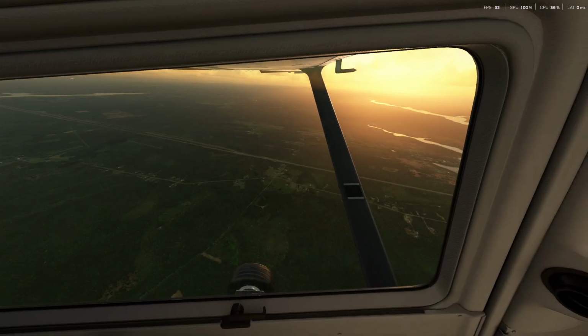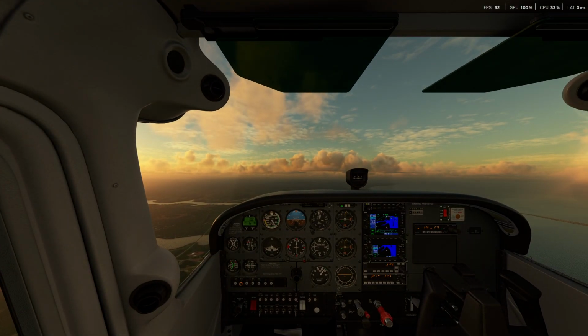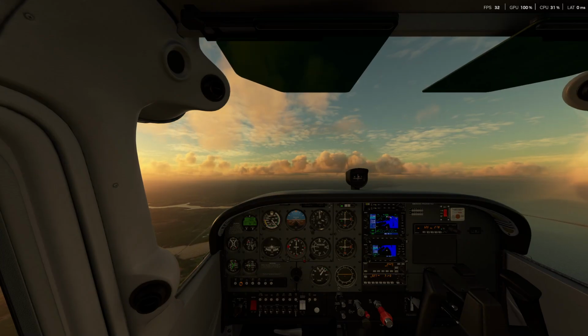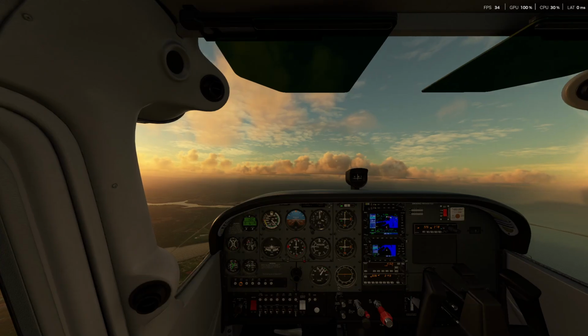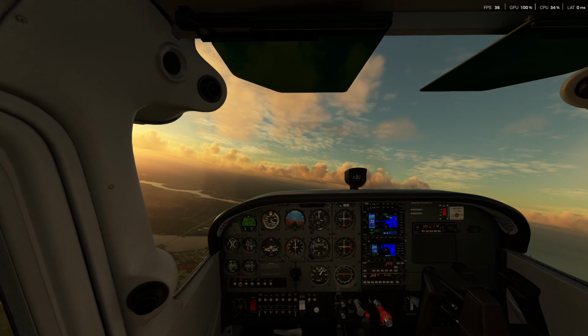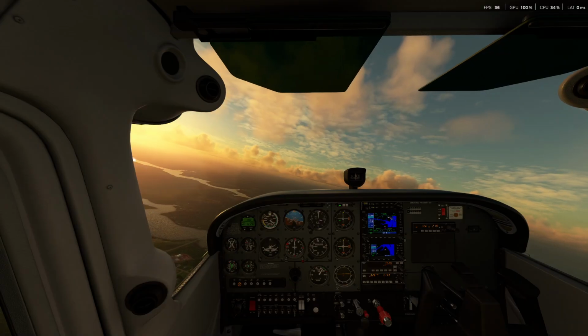We're almost at the end of 1 Charlie, so we're going to go ahead and turn around. What we're going to do is get the reference data for your turns and legs. The normal, general turn is about a 15 degree mark. It's a standard rate turn. So you want to do a turn to the left here, heading back to the south.